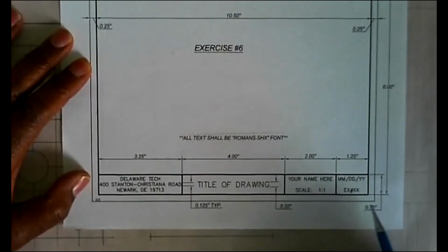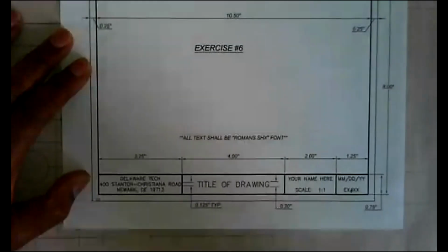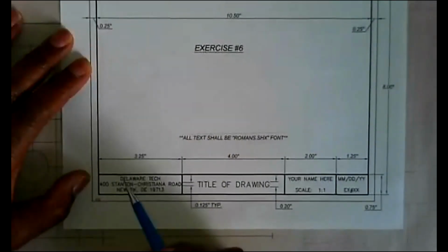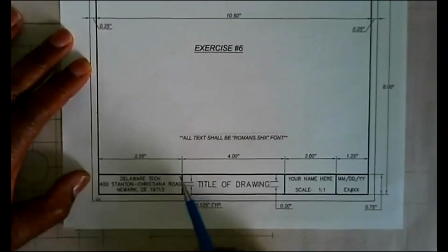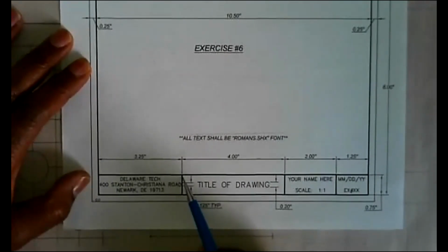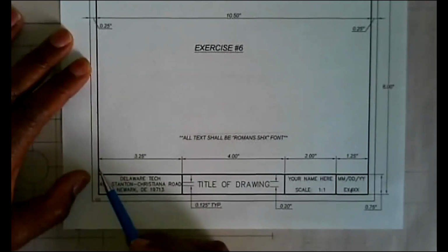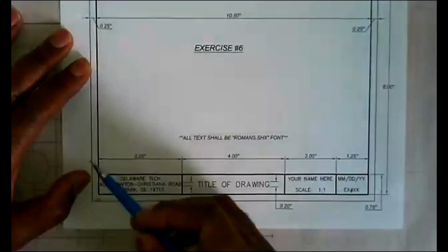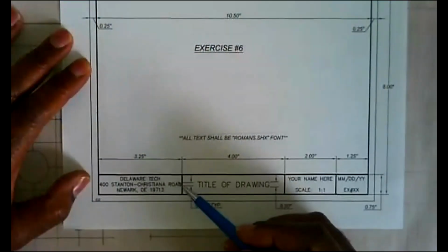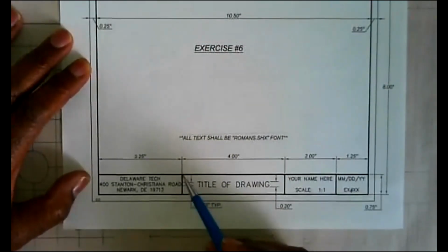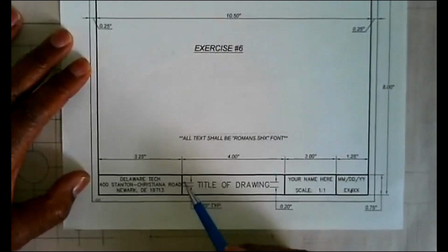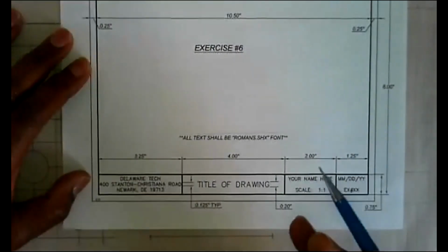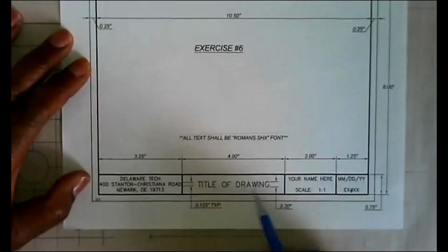Right? And then I'm going to tell you what we're going to do holistically. Then we're going to offset this line from this line by a dimension of 3.25. It's going to be a long line, but then we're going to trim it back down to this distance here, which is 0.75. We can trim it, so we're going to use the trim command.